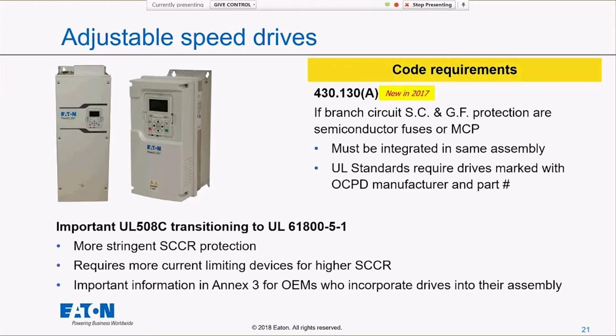So this usually isn't that big of a deal. It's not that hard to just feed it with class J fuses or class T fuses. A lot of times that's what's specified in front of the drive anyway. But it was an addition made in 2017, so I just want to make sure everyone is aware of it.